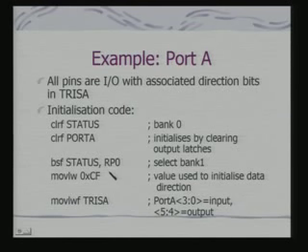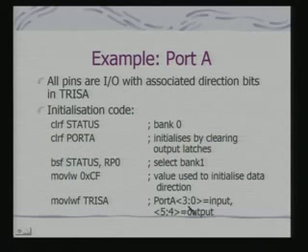1, okay, and using the bank 1 you are writing what? You are basically writing onto this TRISA. TRISA is a control port which sets the direction of the pins on port A. Is this clear? So, once we write the appropriate data, this has been now programmed so that bits 0 to 3 are programmed as input and 5, 4 as output.